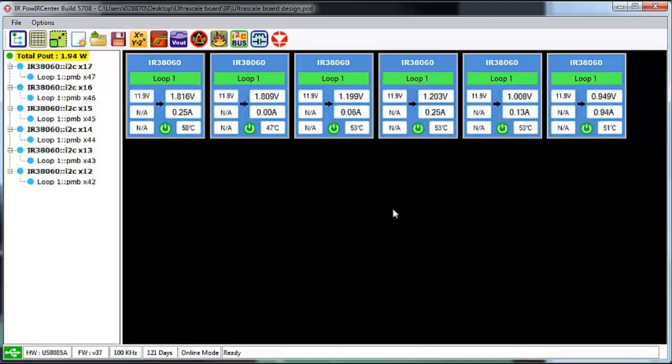One thing in particular that I noticed was that in certain conditions with certain bit streams loaded in the FPGA, the current consumption on the core rail continued to climb. What I was running didn't really have anything additive going on, which led me to believe that we may have thermal issues with that particular design, which would be indicative of us possibly needing a heatsink for an application running this type of design. So things like that, abnormal current increases can point to thermal issues.